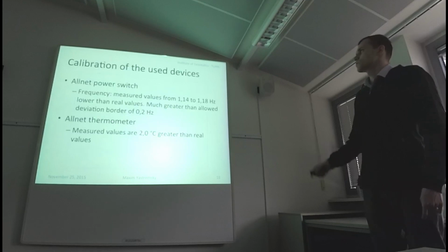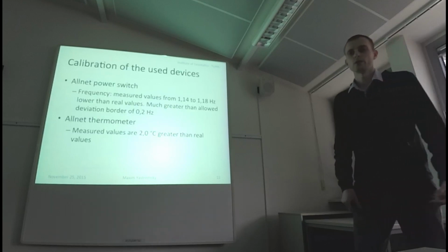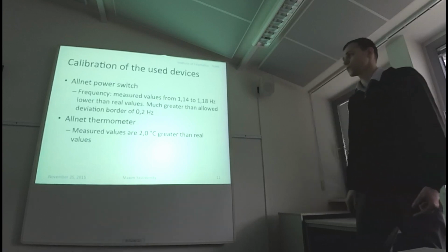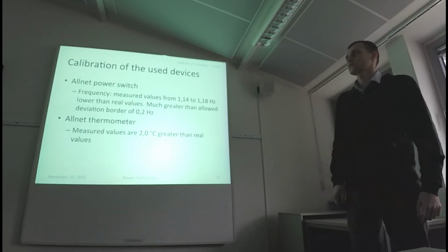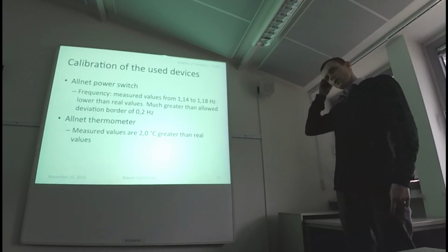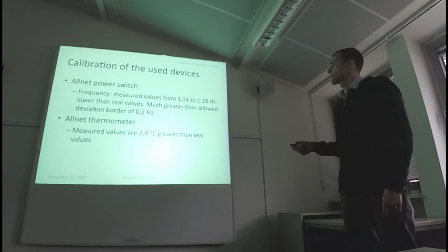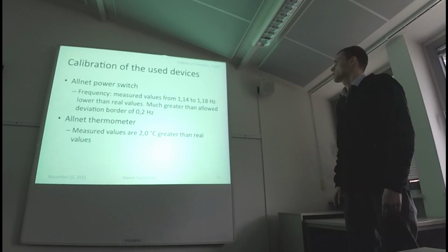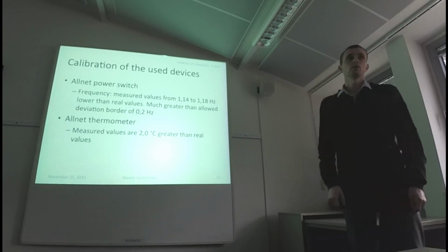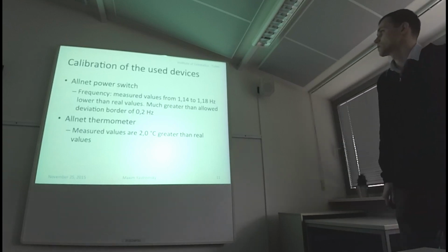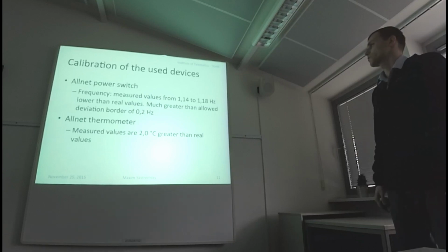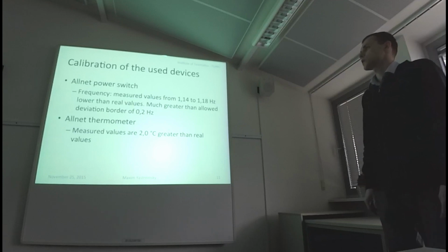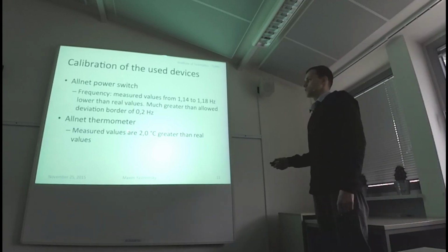Yeah. So before implementing this approach, I conducted the calibration of the used devices. The power switch which we used actually wasn't really accurate. The frequency measurement returned by the power switch was from 1.14 to 1.18 Hertz lower than real values. That's actually a big mistake, and that makes the device actually inappropriate for these experiments. But I will say in a minute how we overcome this inaccuracy. And this was the device we bought.